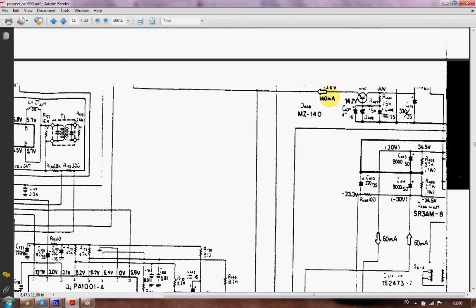So I had not 10.0 volts on this side, I had 0 volts, while I still had 30 volts on the input. 30 volts on the input, but nothing on the output, and the base had its intended 14.2 volts. So that would almost guarantee me that the transistor had failed, since there was no output.